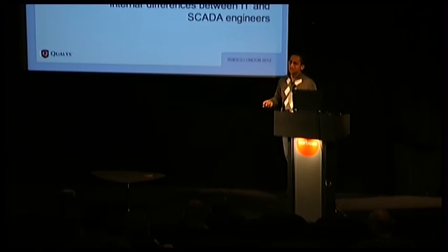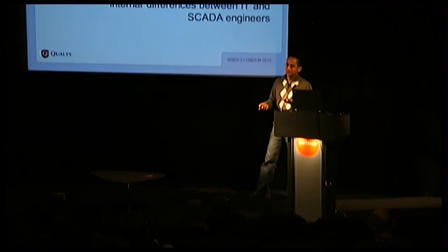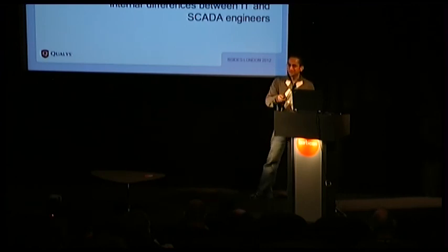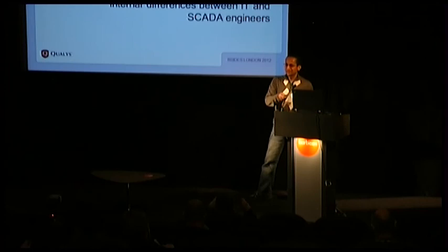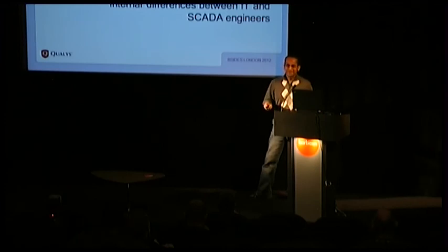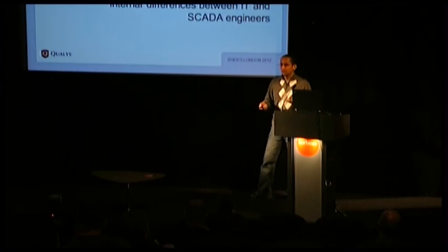So if you are an IT person, and you have the task to scan a SCADA system, first really know what you are scanning. Ask your vendor if their tool has ever scanned this type of SCADA software before, and is it safe to do it? And even if the vendor says that it's safe, do it when there is a maintenance window. Every factory or industrial floor has a few hours of maintenance once every quarter or once every month to clean up all the parts or things like that. So take that opportunity to do it.